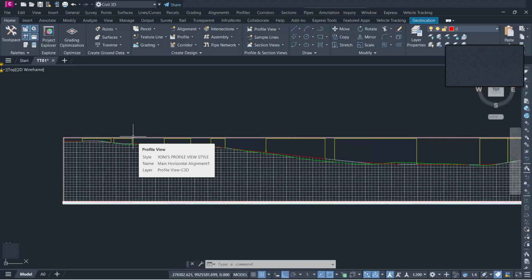kind of materials that you're finding. Because remember, when you're doing the alignment soil sampling, you are sampling in a zigzag manner. One point here, the other on the opposite side, one at the center line, the other on this edge. So sometimes the geology of an area is not uniform. It varies. The soil formation varies from place to place. So then what do you notice? You find that there are a lot of surprises.